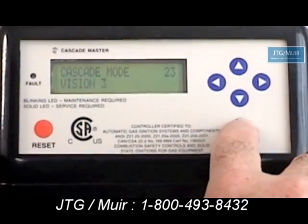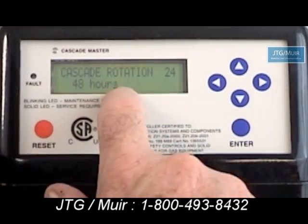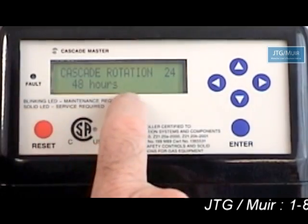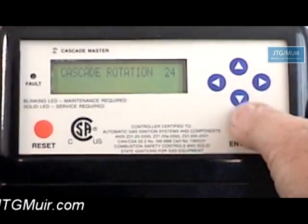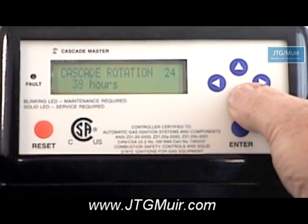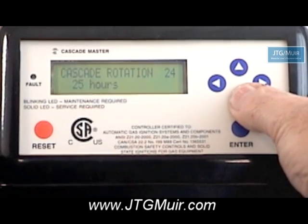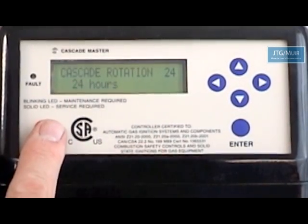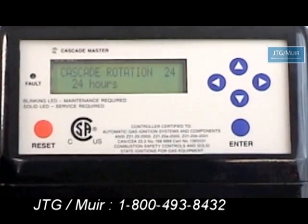Vision 3. Next one. Cascade rotation. These boilers will rotate based on hours of runtime. I can go from 48 hours, which was the default, factory default. If I choose, I can say that I want the boilers to rotate every 24 hours. Enter. What that means is every 24 hours the boilers will take turns starting up.